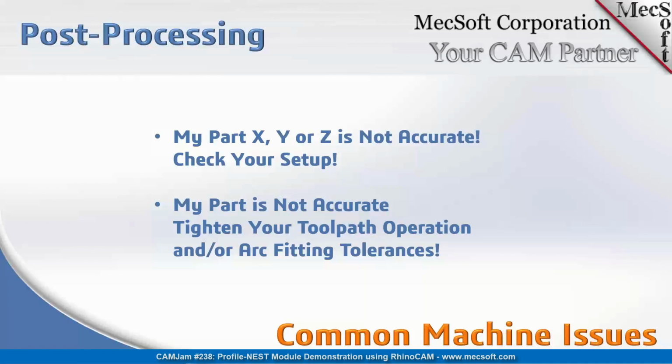If you have arcs being fitted, make sure your arc fitting tolerance is 2 times the global tolerance. If your arc fitting tolerance by default is 0.1 and your global tolerance is 0.001, then you could see some arcs being fitted incorrectly. If they are fitted incorrectly, in most cases you will see that on the graphic display of the controller.